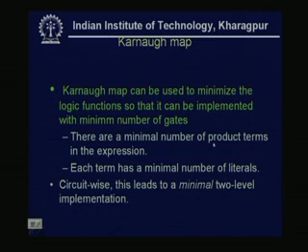Now, there are a minimum number of product terms in the expressions. So, what do we mean by this minimization using Karnaugh maps? That minimum number of product terms, and each term has a minimum number of literals. So, just now what we discussed was just applying the postulates and the theorems. Today we will be seeing a well defined graphical method by which we can minimize the Boolean expression.